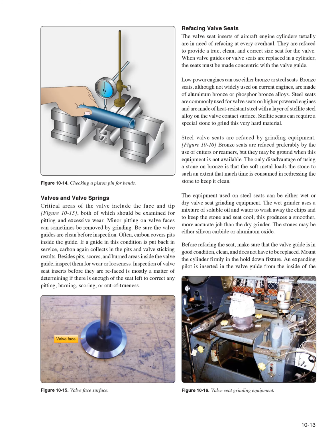Valves and valve springs. Critical areas of the valve include the face and tip, figure 10.15, both of which should be examined for pitting and excessive wear. Minor pitting on valve faces can sometimes be removed by grinding.